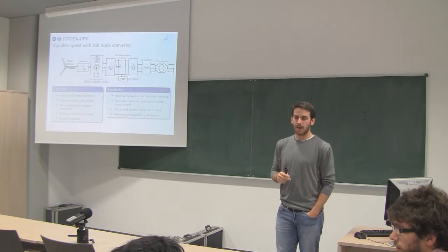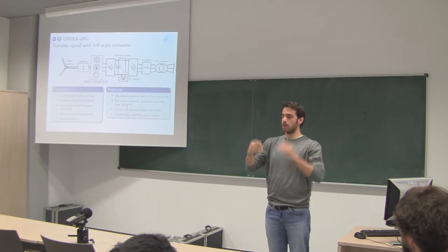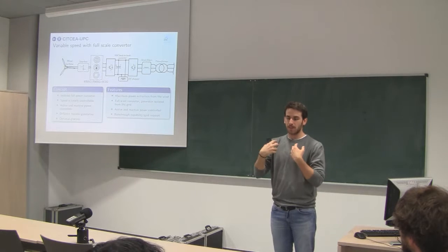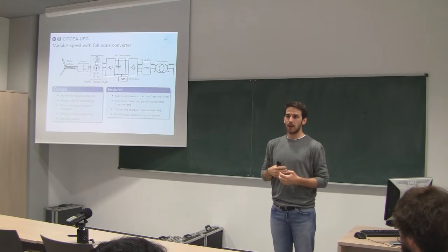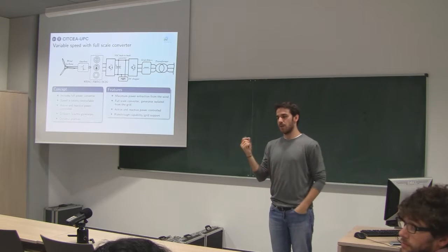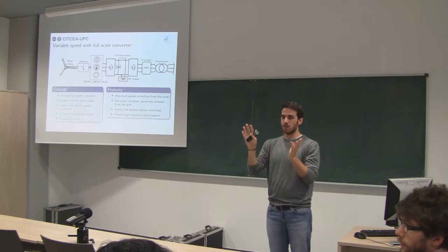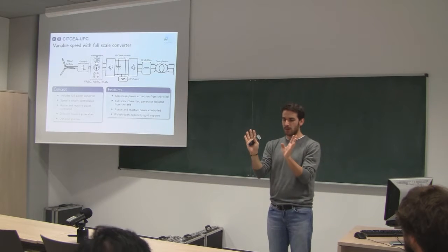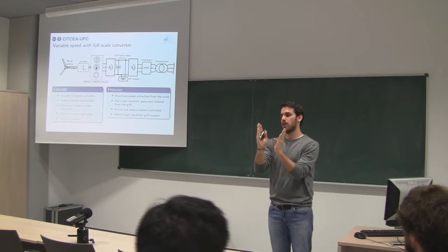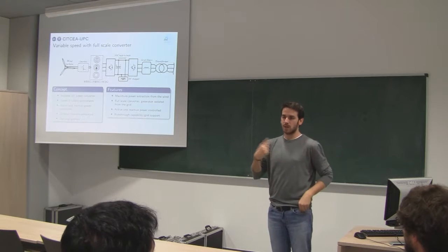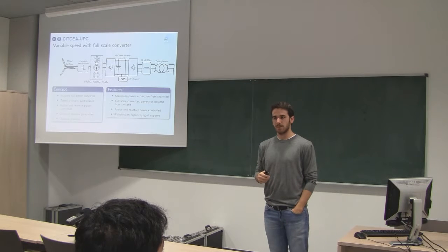Will destroy the machine. Yeah, and then what they do is they disconnect everything and they pitch the blades totally in order to not absorb any power from the wind. That's what they do fast. So the pitch is also used to start the machine. They start rotating the thing, moving the blades a bit from 90 degrees. I would say they start pitching until they can start the whole machine moving.